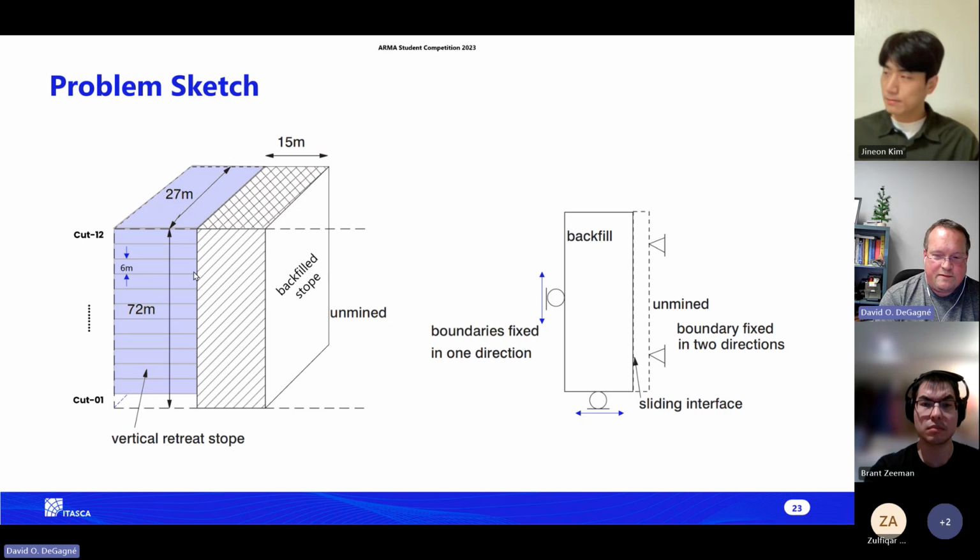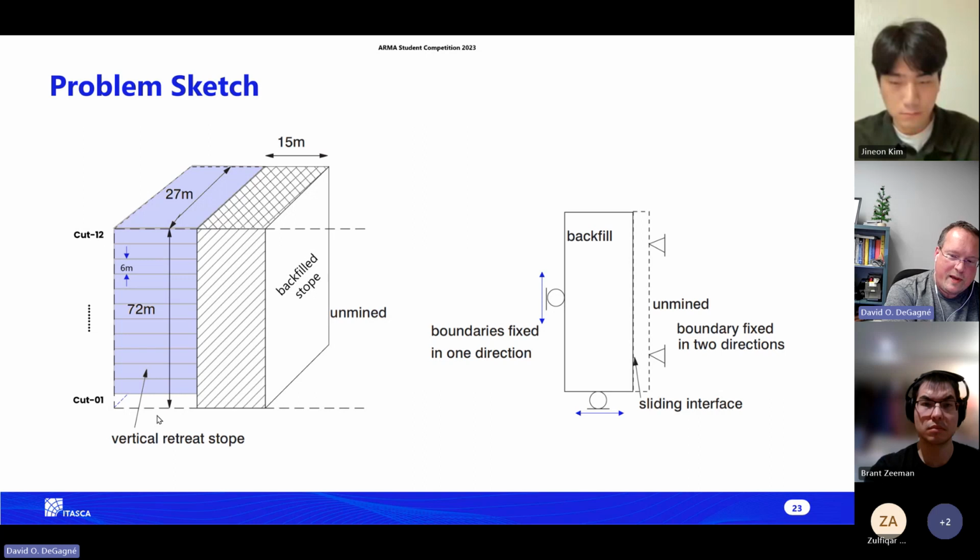So the displacements at this face are in the meters. That's inherently unstable. It's not likely to come to equilibrium, but it may continue to move and move and move further out. Again, because we're running these in large strain, you'd physically see that wall move.